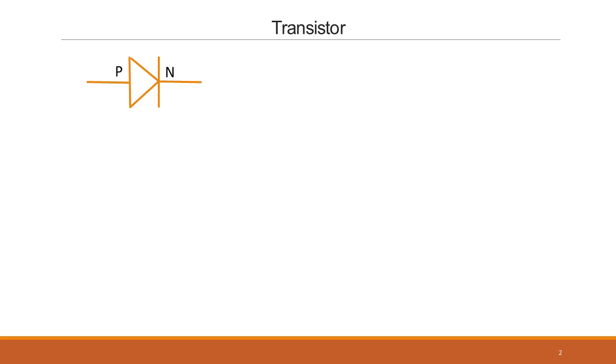So far in the previous lectures, we've seen what a PN junction, a PN diode, is. This is a symbol where we apply a voltage across its two terminals and I get a current through the two terminals. Right? The voltage across the two terminals controls the current through it. It's almost like a resistor, except that it is non-linear. You see that in the forward bias, the resistor value is low. In the reverse bias, the resistor value is very large.